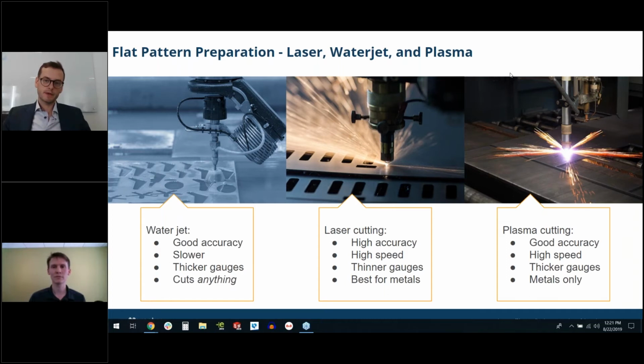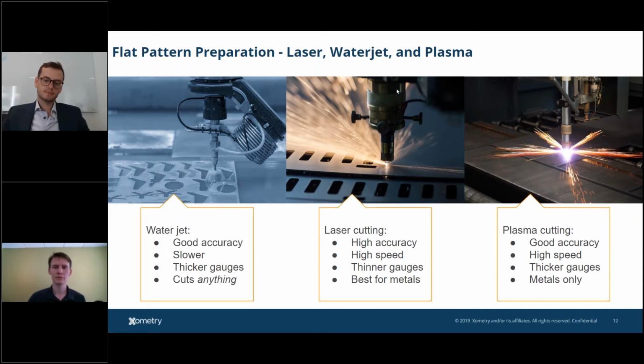CO2 laser can't cut reflective materials, kind of slows down on some blends of stainless, right? Fiber laser is between 1/3 and 1/10 the size. The beam is literally 1/10 of the size, but it has twice as much energy, right? So it's very, very condensed, and what you get because of that is you get incredibly crisp edges. So what we're seeing right now with our 4 kilowatt laser is we're seeing a lot of small gauges with no finishing afterwards. So, yeah.